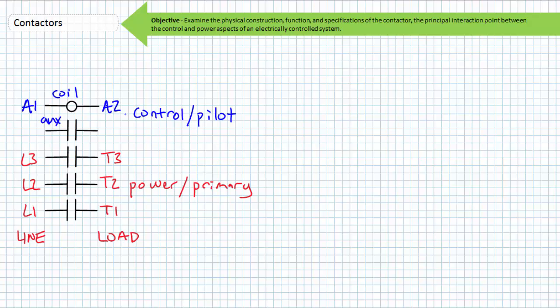A disclaimer before we continue. Always consult the manufacturer's datasheet for the specific contactor of interest. Do not for a moment assume the pinouts and specifications presented herein are universal in nature. A thick, tangled jungle of not only NEMA and IEC differences, but also manufacturer-specific terminal numbers and idiosyncrasies exist, especially for older contactors. This being said, most manufacturers now offer dual NEMA and IEC numbering schemes, with the IEC numbering scheme becoming more and more accepted because of its standardization and ease of interpretation.